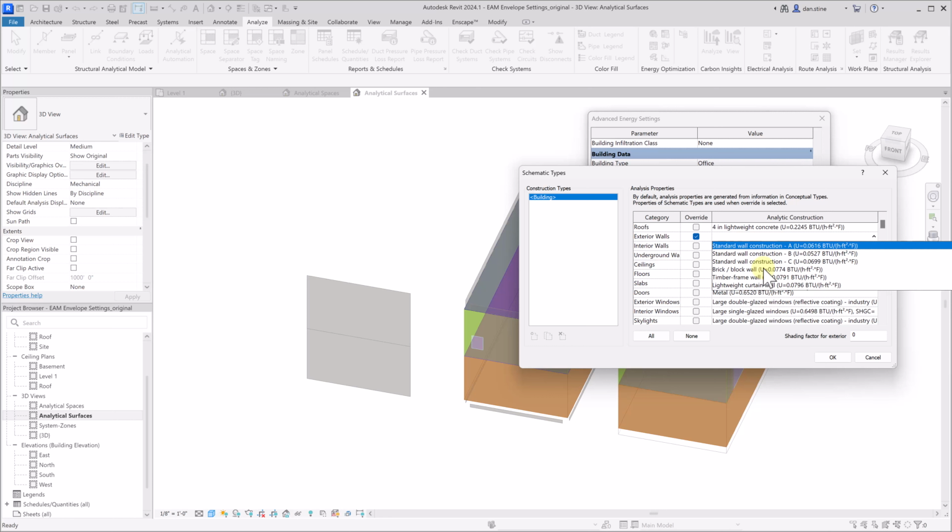They don't list the thermal mass, which is a really important component, so you need to make sure you pick the correct thing, because just picking two wall types that have different R values aren't necessarily going to produce the same results if they have a different element in them that has a substantially different thermal mass aspect to it. But we can type something like straw bale and see that there's a straw bale wall type.